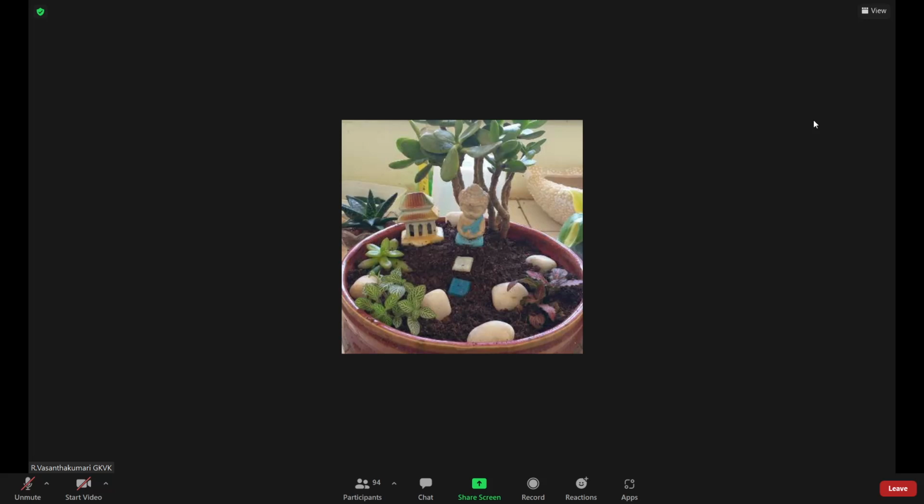Next are the compression rings, also called piston rings. There are two types: the compression ring and the oil ring. You can see the sketches. What difference do you observe? The oil ring has holes on its surface. Why are those holes provided?